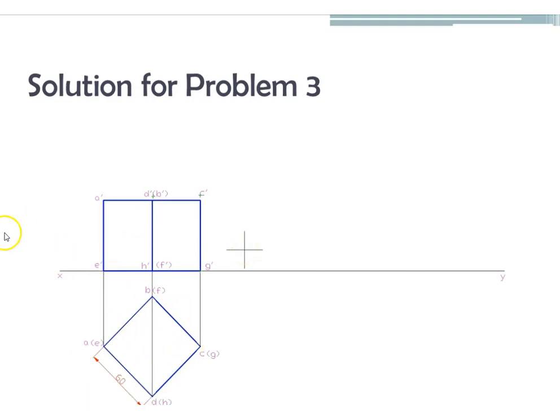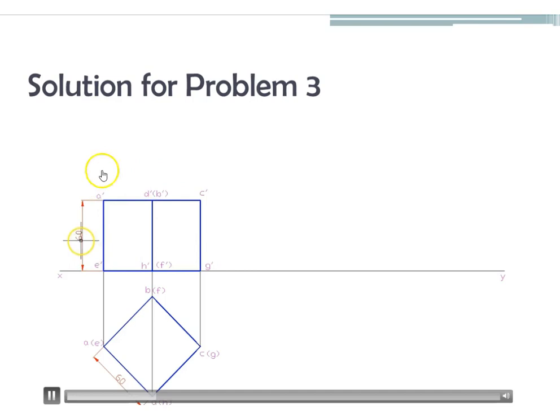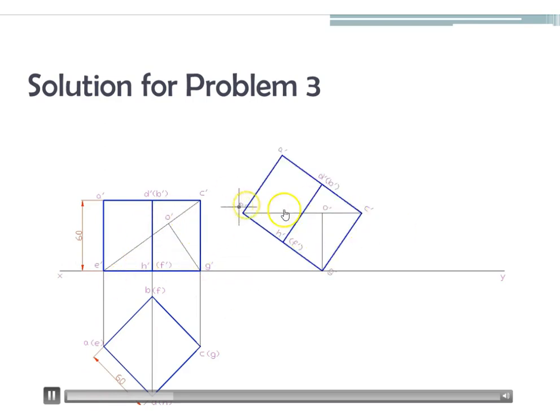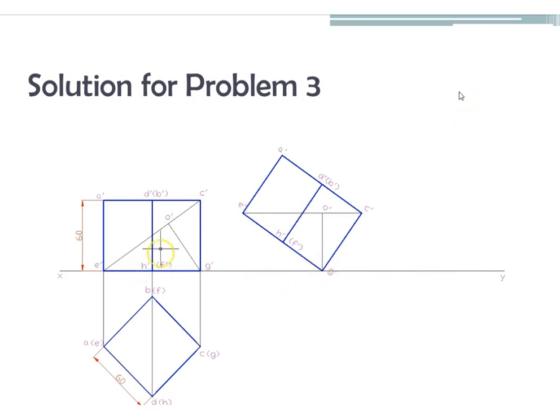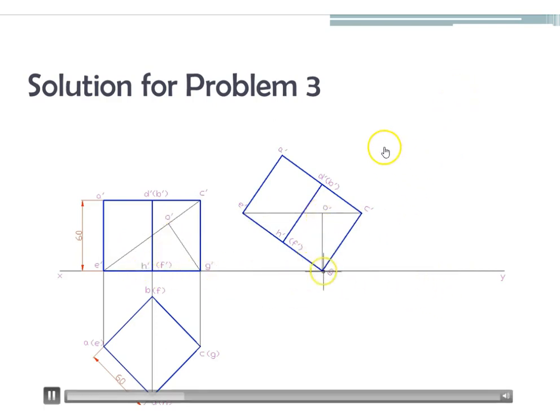So in the next position, what we'll be doing is tilting this solid with respect to this corner, and before that we join these body diagonals E and C. E and C is a body diagonal that has been joined, so that enables us to actually rotate this solid and make this diagonal parallel to the xy line, as we have seen before. So that view is also there. Now the next thing is simply to project it down and project from this view, so that you get the current top view.